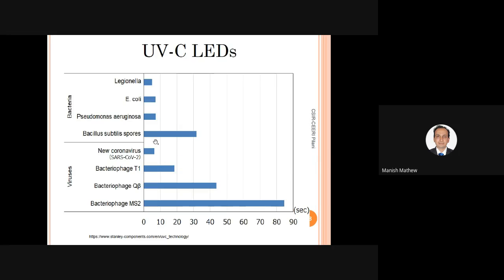Then he exposed it, and I put a UVC LED, not the 265. At that time I didn't have that 265; I had 275 nanometer. He observed the readings after 5, 10, and 15 minutes. What he found was that after 15 minutes, all the E. coli bacteria were dead. After 2 minutes, the number of bacteria reduced to around 20% from 100%. But to completely remove them, it takes some more time. So this was a 1 liter bottle.